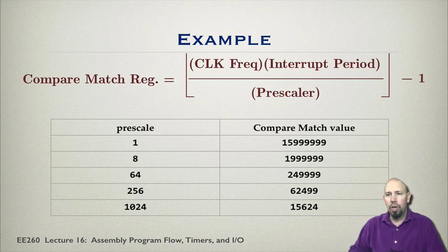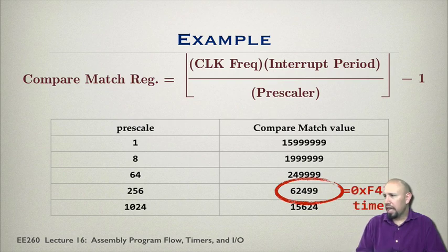There's only one 16-bit counter. And as you can see, for a 16-bit counter, 65,000 is the largest magnitude, 65 something. And so 6200 is the one that we want to use, the one that's below the 65,000.